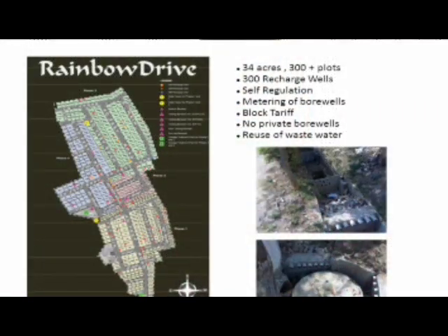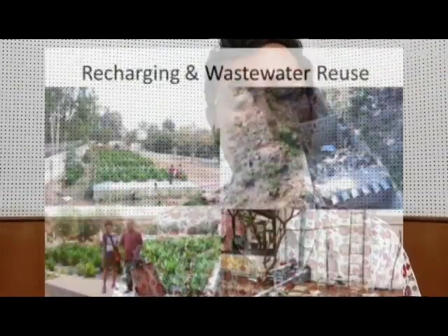It starts with controlling the demand, reducing people's demand. From around 250 liters per capita per day, they've reduced their demand to between 110 and 150 liters per capita per day. And they've done this by metering each household and having their own tariff and ensuring that the basic access to water, the lifeline need for water, is not expensive. But beyond that, people are really paying the real cost of water so that they get disincentivized to be wasteful.